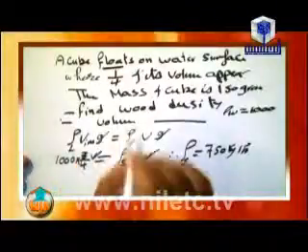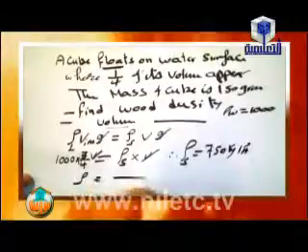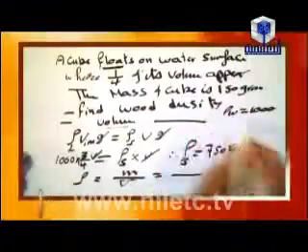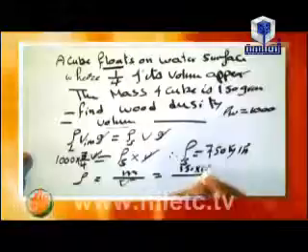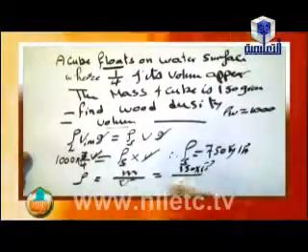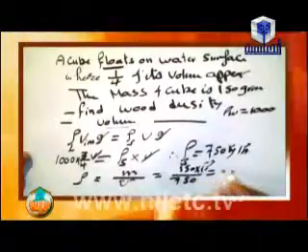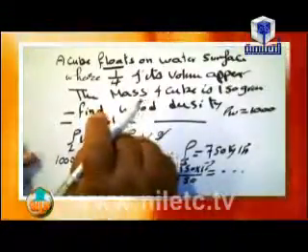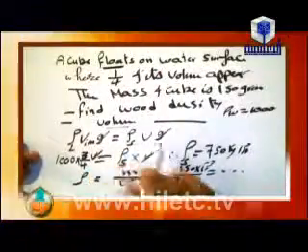So we want the volume of the cube. We know that rho equals mass over volume. The mass of the cube, which is equal to 150 gram, we convert by times 10 power negative 3 to be kilogram, over 750. We can find the volume by using a calculator. So in this problem, we deal with a body floating on the water surface, so we use the rule rho liquid V immersed g is equal to rho solid V times g.